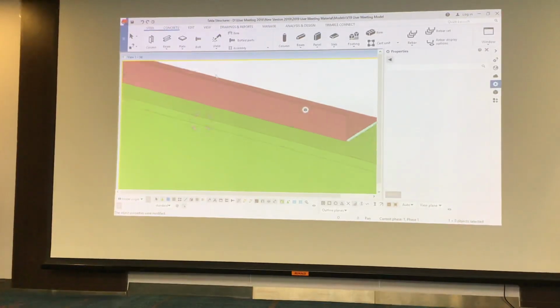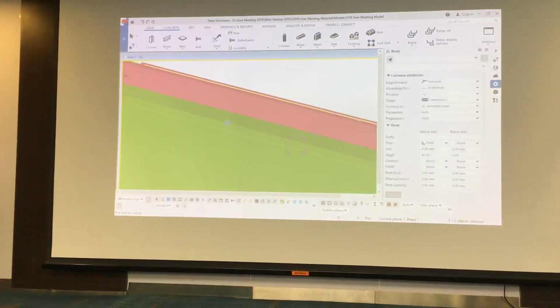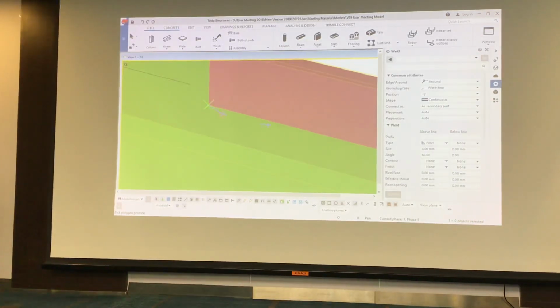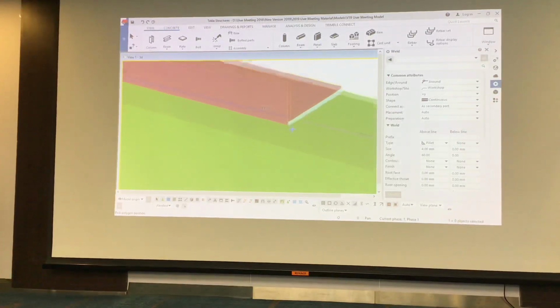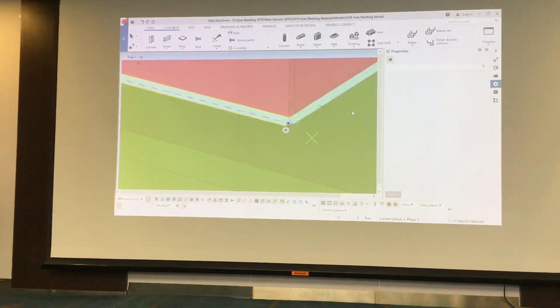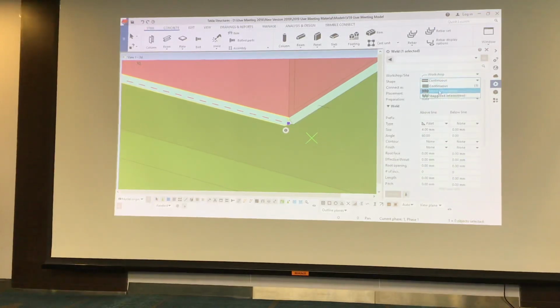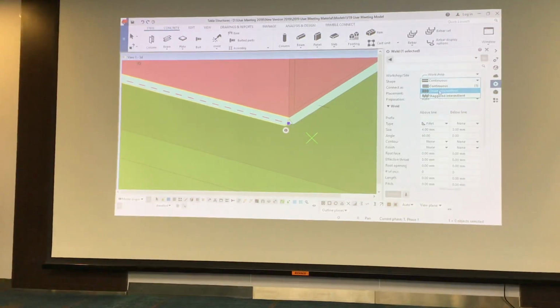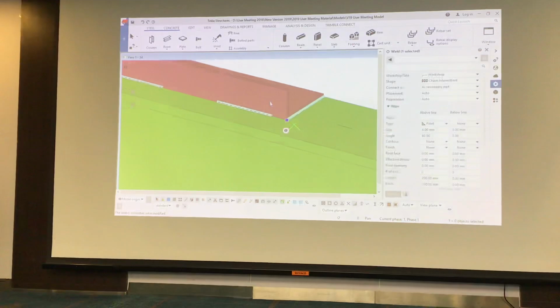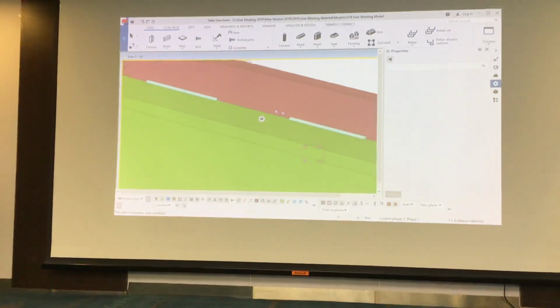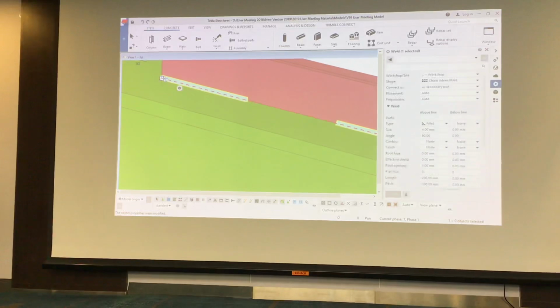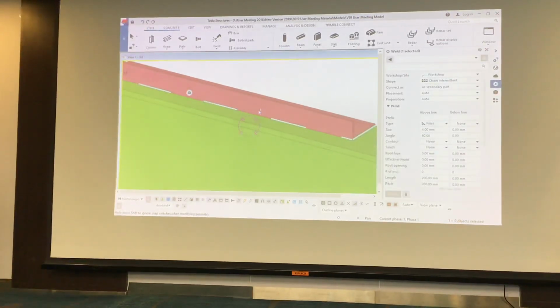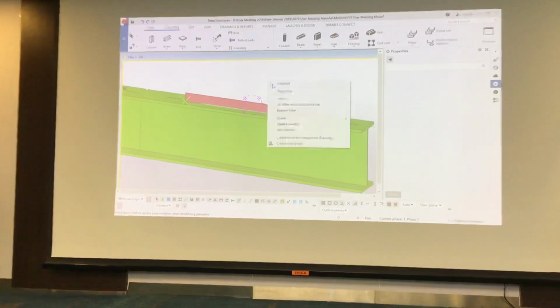There, like that. And then we'll have another weld here, polygon weld, this to this, and we'll say it goes from this point here over to this point here, and then on this particular weld I will say that weld is staggered. So for built-up beams or PEB, this is what you do. So it's staggered like so, and we'll say it's 200, miss 200. So that's the sort of stagger on there as well, like so. And that's then how you do these staggered welds. Again, you can pick that up and you can move that weld and say it starts there. So you can easily now move and manipulate these welds.